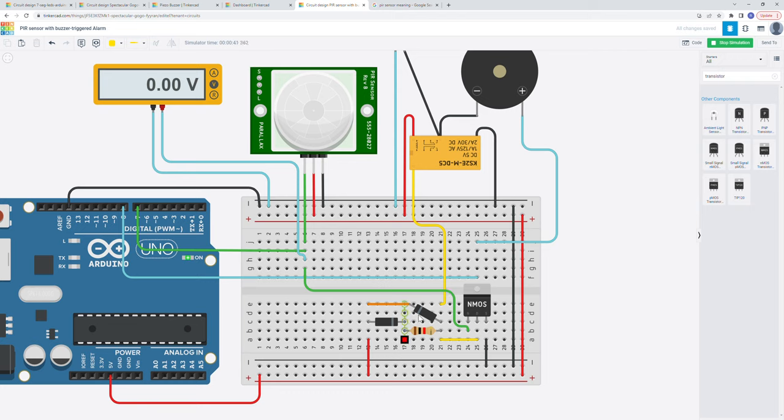If there was no path to conduct the current, there would be an immediate overvoltage or undervoltage, overshooting or undershooting, at the supply of the circuit. So to avoid it, the diodes are connected in parallel and are placed at the ends of the relay coil in the opposite polar direction. Having this current pass through the diodes will avoid any adverse effect on the power supply.